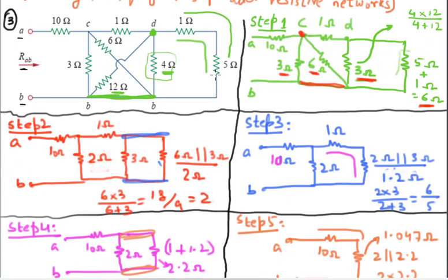On the left hand side, you can see that 5 and 1 are in series. So in this method I'm going to start from the very right hand side, and then keep on writing the expression and move towards the left, finding out which resistors are in series and which are in parallel. But you should only do this when you have much more experience.